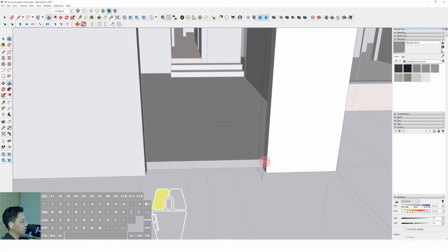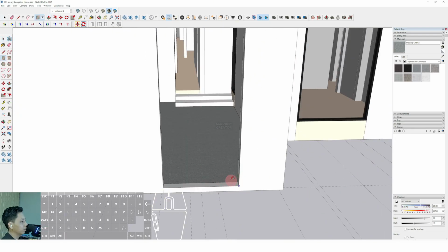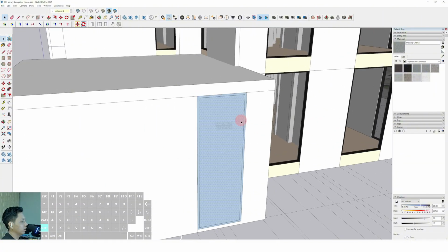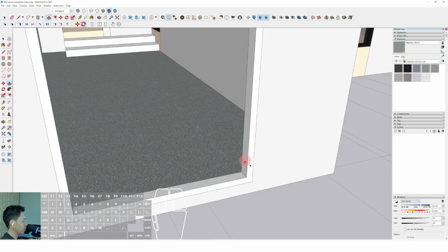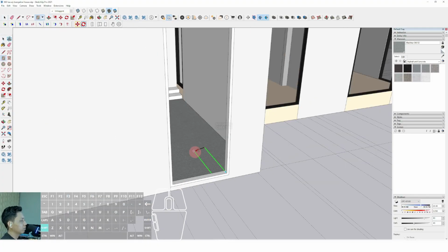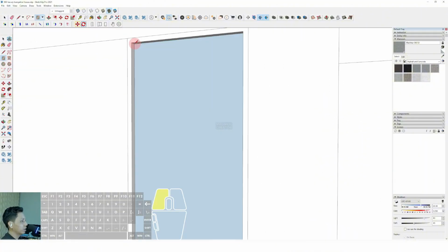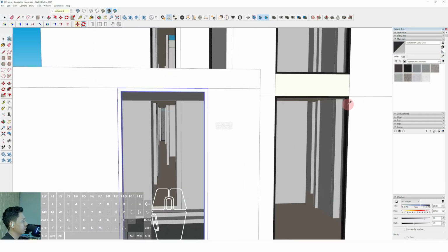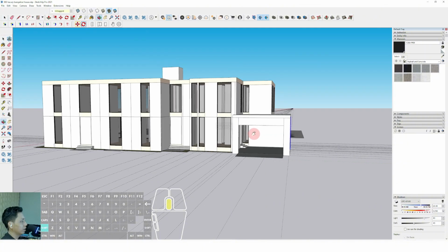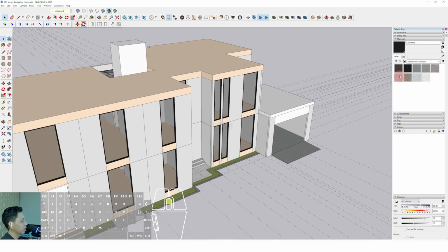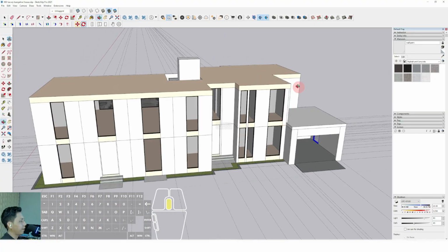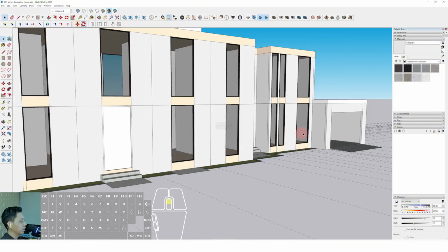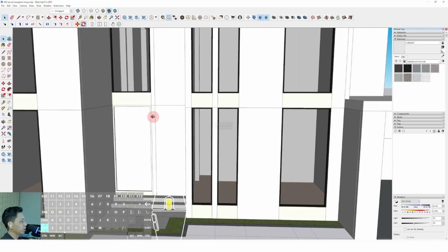it with the wall, using the wall. Okay, then we can make the window in here. Okay, and erase and push it to the behind 120 millimeter, and draw the rectangle to make a glazing, and assign the glazing and triple click, right click and make group, and assign the black color in here. Okay, and now we can assign the materials first. Okay, it's almost complete.